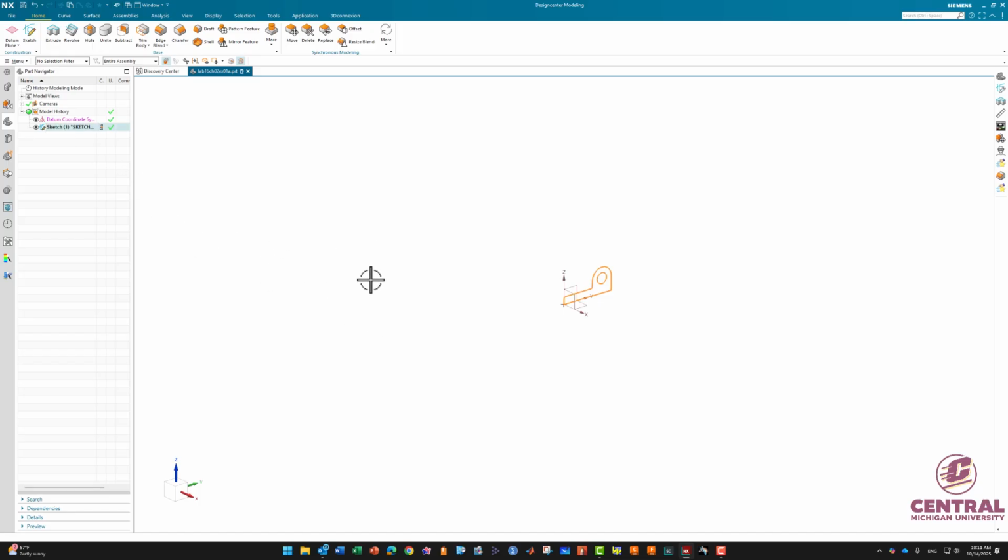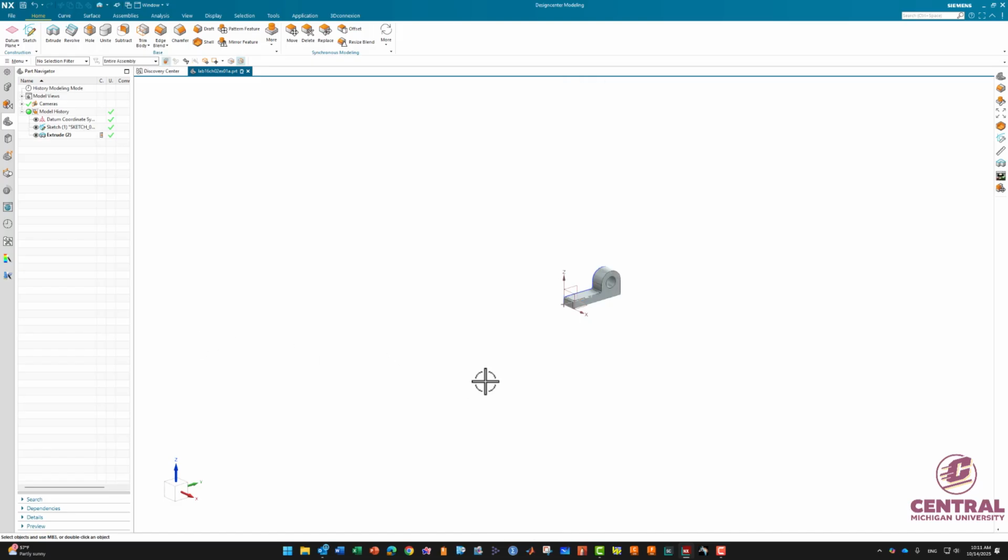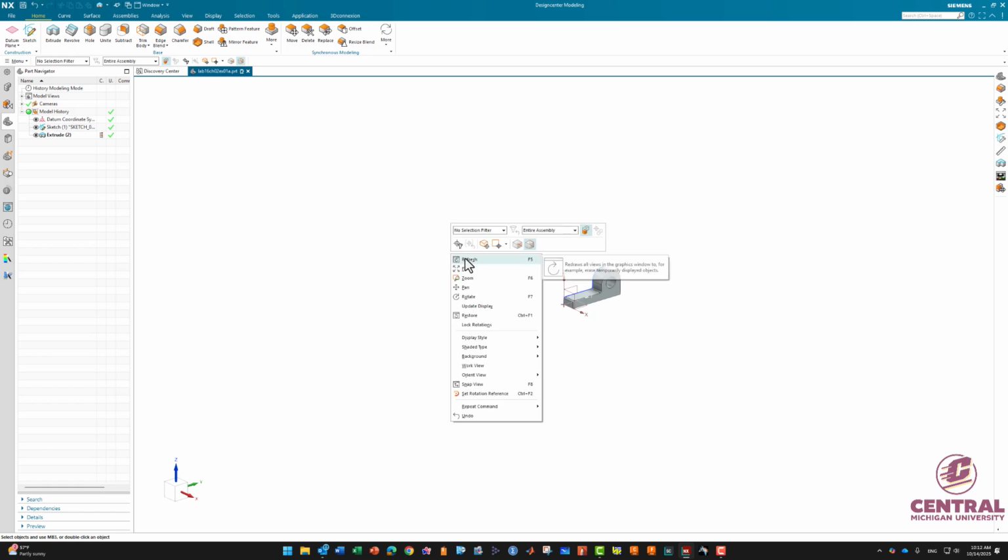If you want, you can just right away extrude it to confirm that everything works fine. Let's give it a 35 millimeter extrusion. We'll talk about this more later. Say okay, then right away the sketch becomes solid. So if you press the HOME key on your keyboard, or right click over the empty spot, there is orient view and trimetric view. So again, as you can see, the key is HOME on your keyboard.